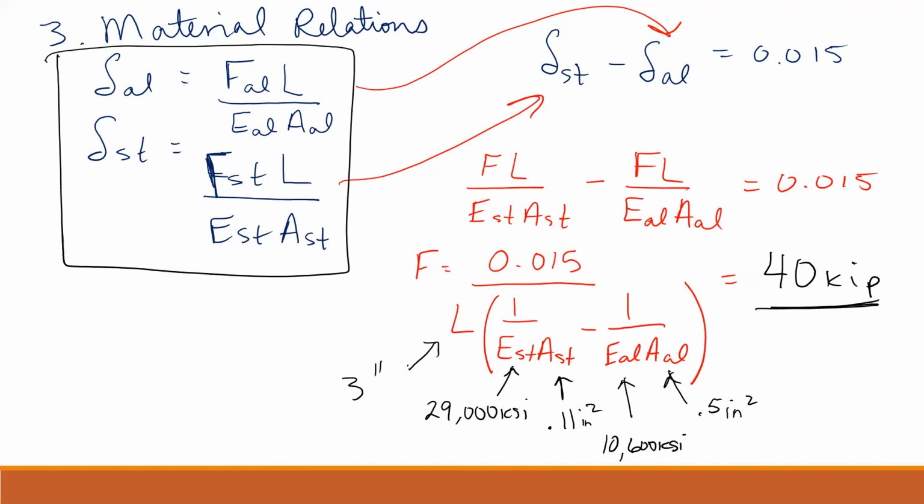Then one of those fractions, the aluminum one, would drop out, because you get rigidity by having an infinite E value. So you plug infinity in there, that fraction becomes 0, and you could solve your problem that way as well.